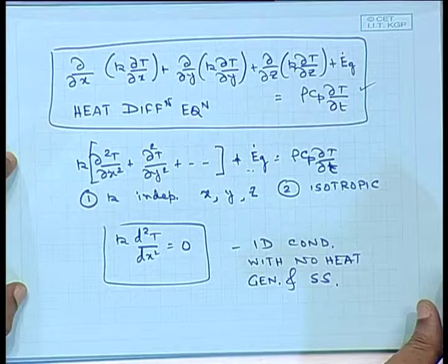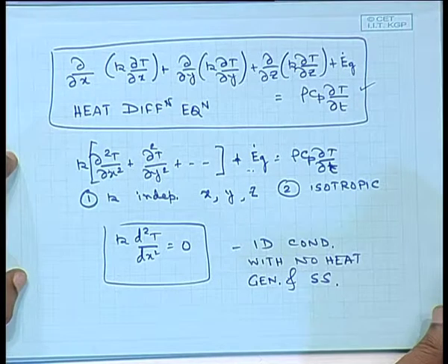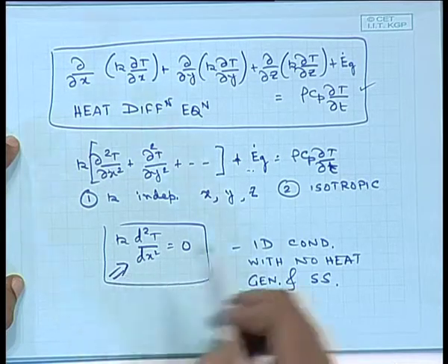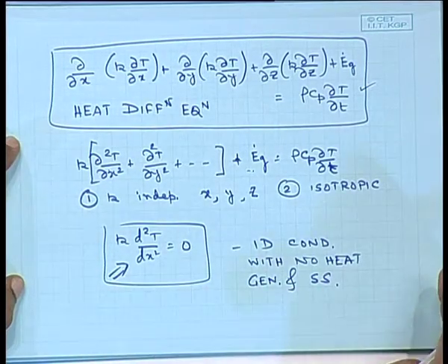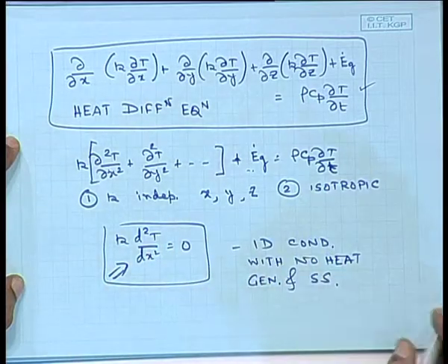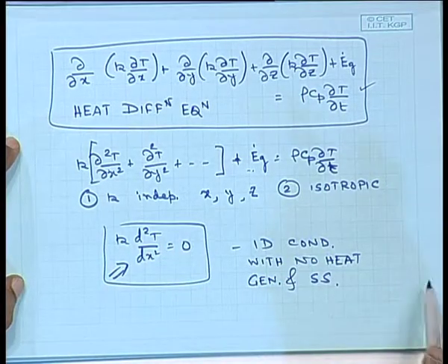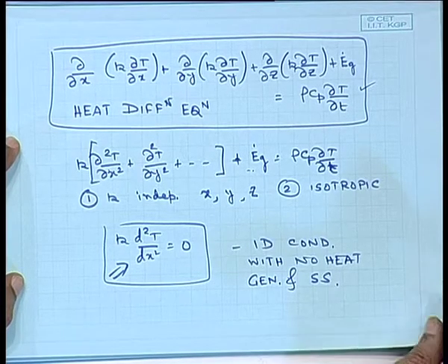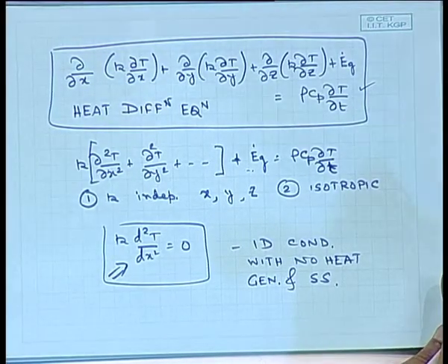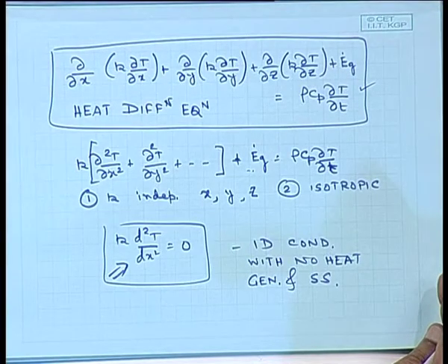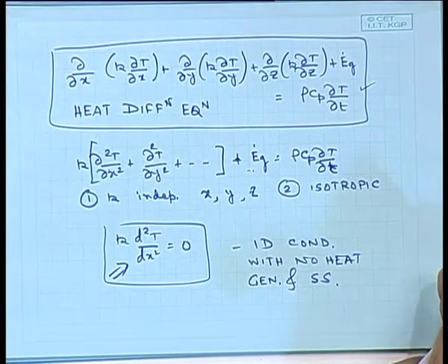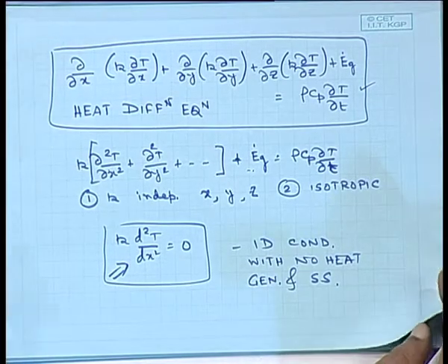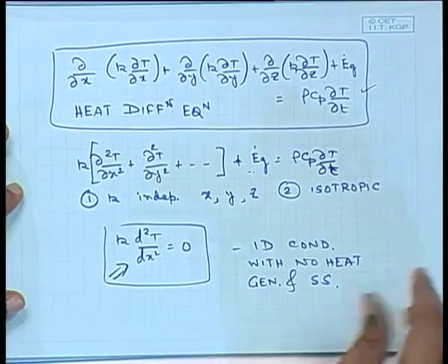At steady state with no heat generation in a plane wall, this would be the governing equation for temperature, and by solving this equation with known boundary conditions, you would be able to find out the temperature distribution inside the solid object. For cylindrical and spherical systems, the equations have a slightly different form, which you should be able to find from your text.